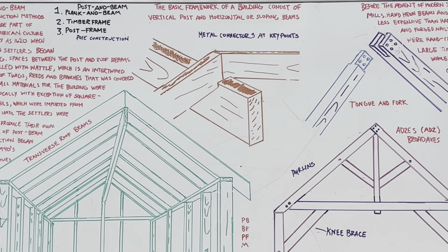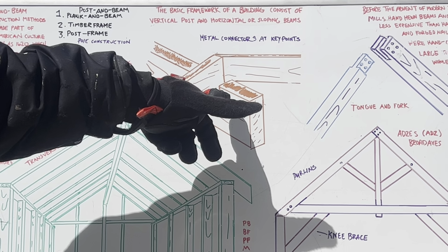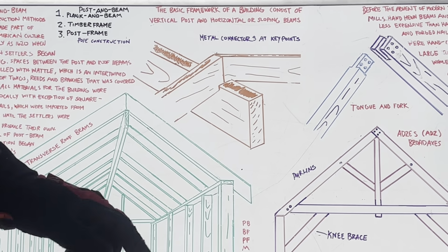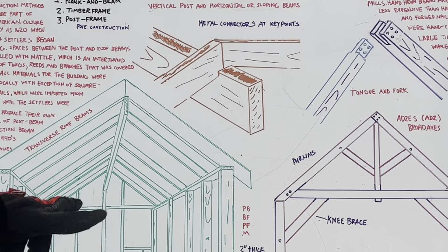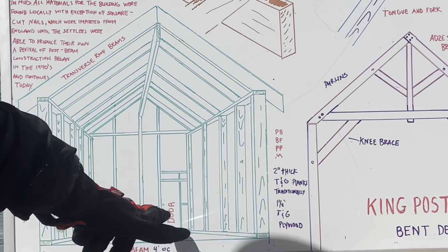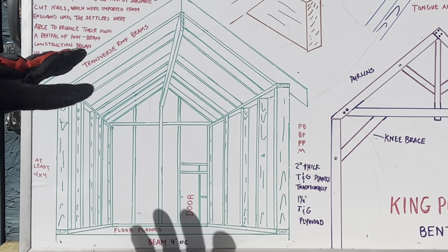But if you did that too, you have to fasten it with joist hangers. Yeah, you can use joist hangers for that connection right there. All right, so let's look at this a little bit more. You got right here, you got your door, and also the difference.